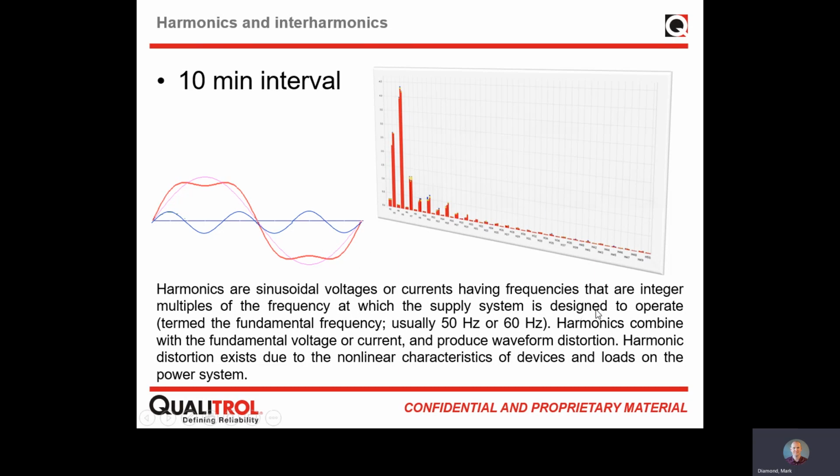And we know that harmonics can be damaging to equipment on the network as well. So like unbalance, unbalance can cause extra heating in transformers. Harmonics are something similar. So people may look at a transformer and try and gauge the rating of a transformer, but not take into account harmonics, which will cause the transformer to be pushed even harder than it's supposed to be. So these can have damaging effects on other equipment on the network.